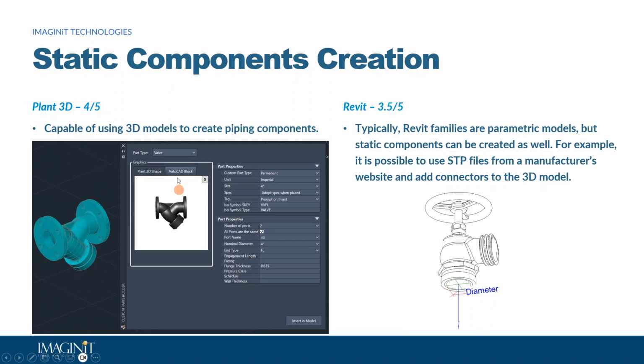So this is a strainer. It's actually showing as, or maybe it's a check valve, not sure. But over here, it's set as valve. And then you, over here, just set the different properties and the flange, and then you create your component.